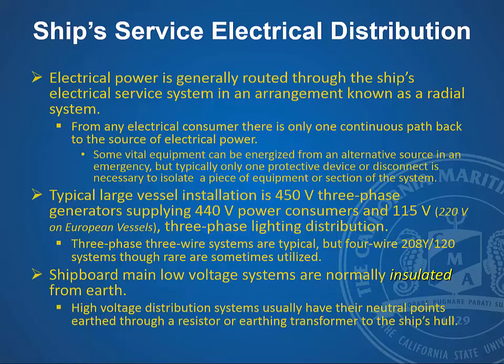But for safety reasons on a ship, we don't necessarily want a circuit to trip. We want that equipment to continue to run until the operator has time to switch over to the redundant system and turn off the system that has been grounded.